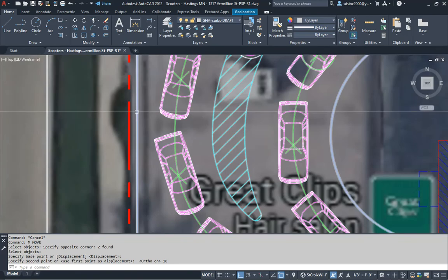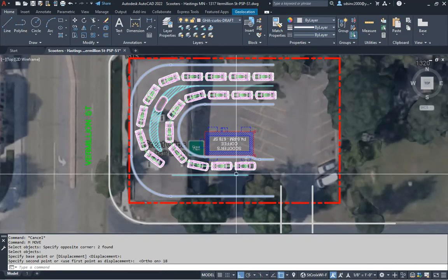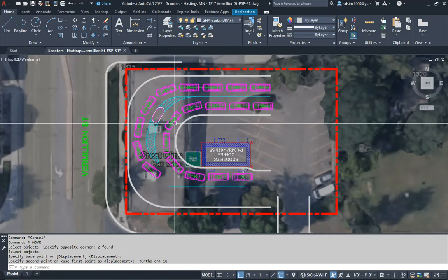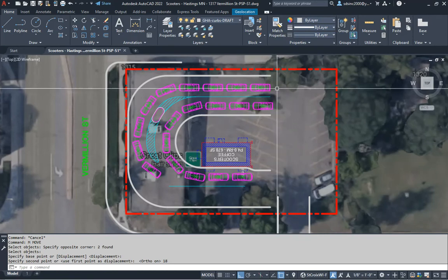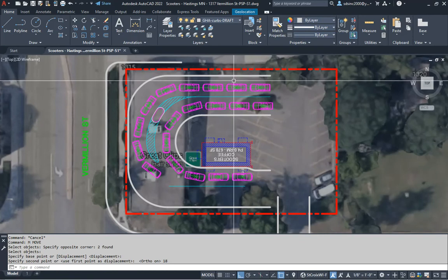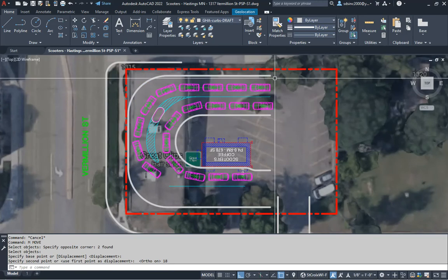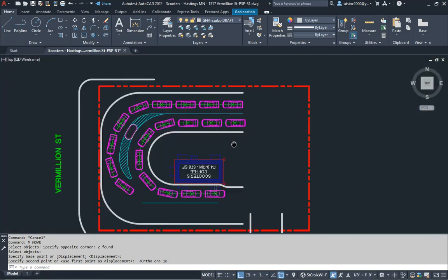Once we offset our curb back, we'll have a foot left of green space. And as far as north and south here, I just centered it on the property. You do want to pay attention to where existing concrete is, which just worked out really good in this one because when I centered it, it looks like it's landing where the existing concrete is.